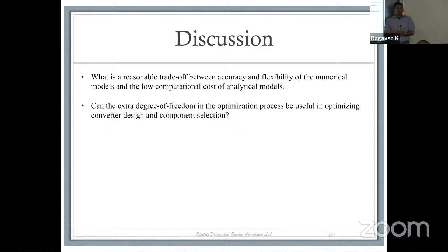You cannot assume that the DSP 2407 is going to be effective. You might go to 2812, it's still not effective. And then you go to 28335, you have 28377. All of these are TI DSPs, where you go from being a motor-specific DSP to a dual core DSP, right? Now you have more ability to run the system. But what if you are designing it for a system that doesn't have that cost, that space available to put more money into it? How do you accommodate for a hardware-based system, an analog system? Do you have the bandwidth to accomplish something like that?